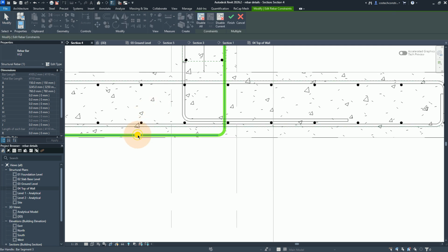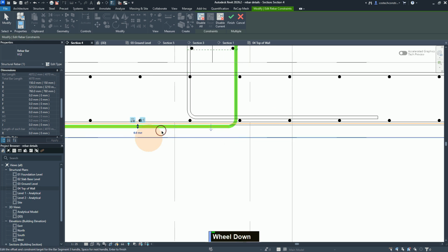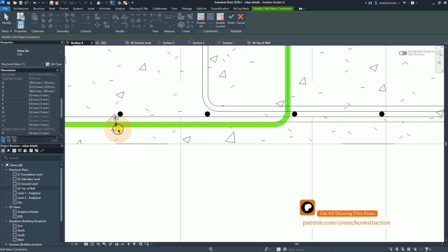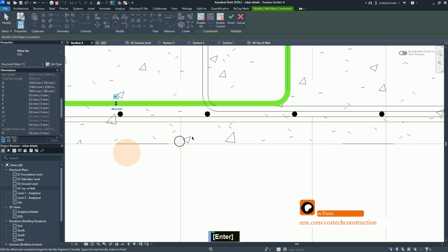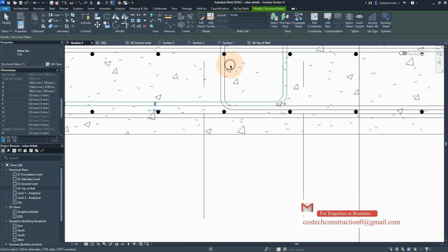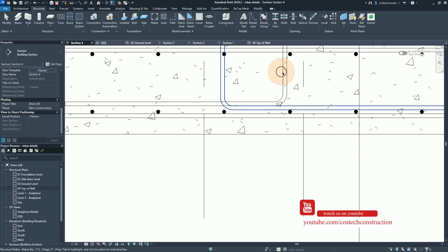We select this bar handle, then we select this Rebar cover. Sorry, we have selected the middle handle. We select the cover. After selecting the cover, we give here a value of -36 to make it above this other Rebar Set here. Now we hit finish, and if I press escape a few times, then select both these two Rebar Sets.